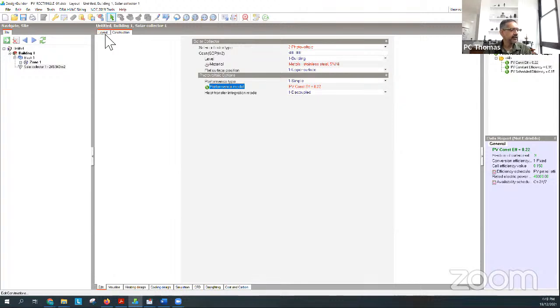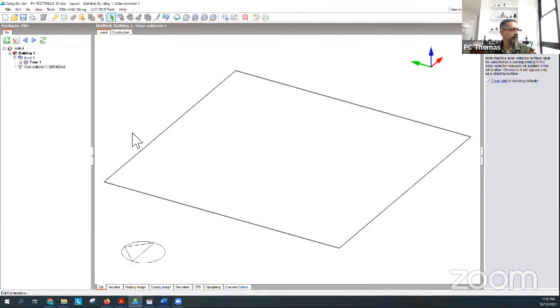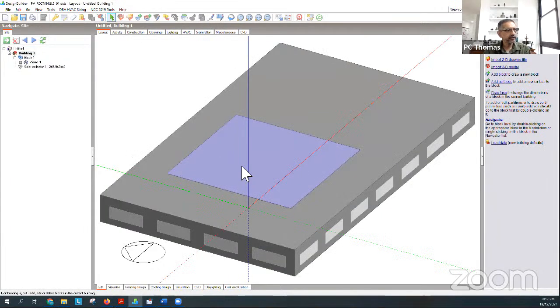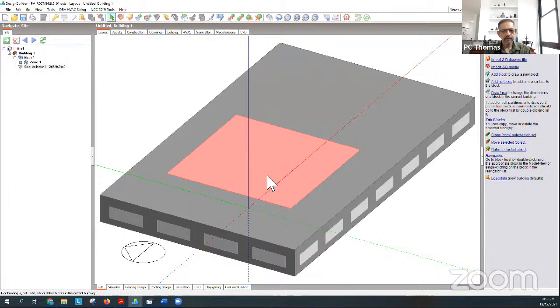It's again, as I said, it's not very complex. It's more working through the process to make sure that you have put everything in correctly, and the model will start working pretty much as soon as you draw the PV system and you connect the electrical load centers. Then it's really a matter of finding technical data to input your selected PV module and your selected inverter with the efficiencies and so on.